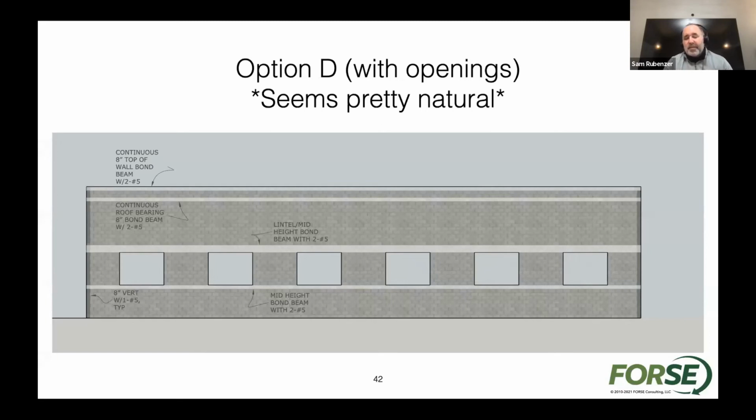So this is the kind of scenario that, even in the Midwest where we're used to putting in control joints, is coming up as, boy, if we have enough openings and they're fairly regular, this can be a really nice design option for contractors to look at. Get rid of those control joints. From an engineer's perspective, boy, that gives me a ton more capacity for this wall. My wall can do a lot more now when I take some of those control joints out. So contractors are happy, engineers are happy, architects are happy, everybody's getting along, I think. So it's a win-win-win all the way around.